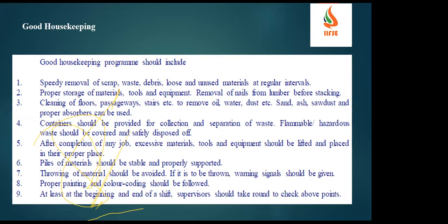Whatever the material, when the job is done, this is the worst case in the construction industry. Simply they will throw all the material and they will go. That must be avoided. While closing the permit, we have to check whether housekeeping has been done or not. In yesterday's permit, we didn't see it in the closing. In the closing status, we have to ensure that the work area is cleaned, and whatever excess tools and materials are there have been cleared from the site area.